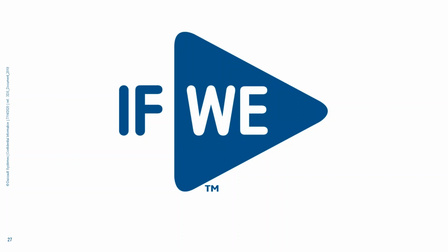One thing I would add to that is macro creation, which is the nice thing with that. If I'm on a network installation with multiple users and I create a macro, essentially a big circuit, as soon as I create that macro and give it a name, it is now part of my database and everybody else can use it as well.